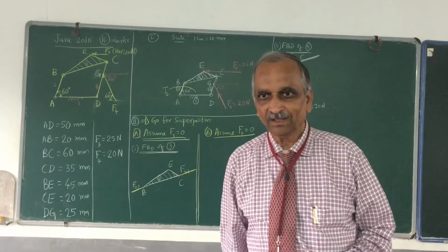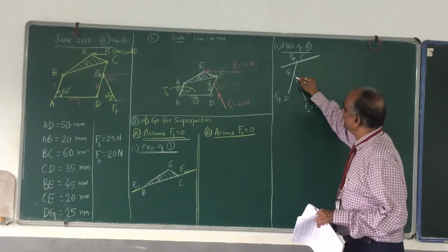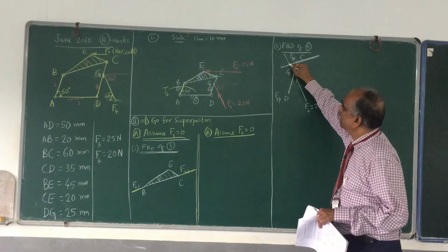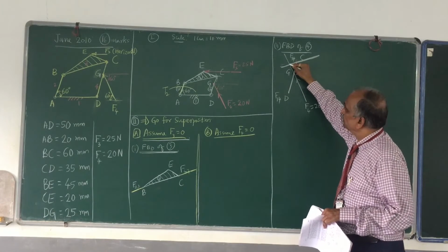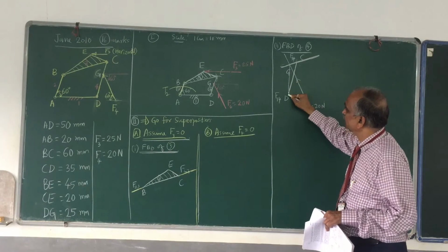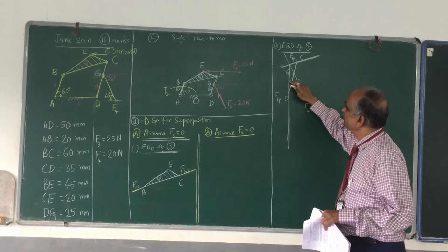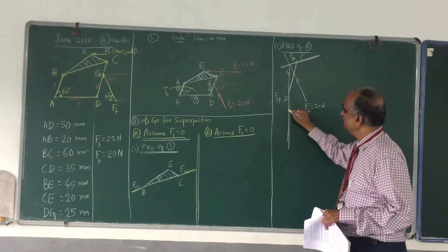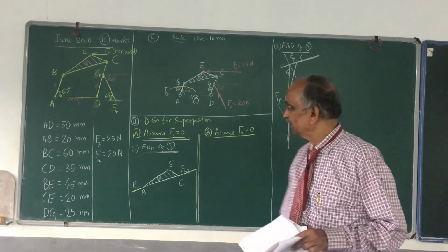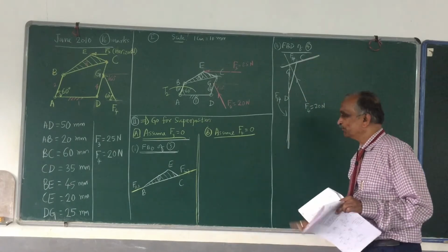This is part 1. Okay, get the common point of F4 and F34 by drawing this line. So this is the common point of F14 also. So draw from here and draw a line passing through D, something almost like this. Please remember, this is the line of action of F14. Now, two lines of action and one force are completely known.